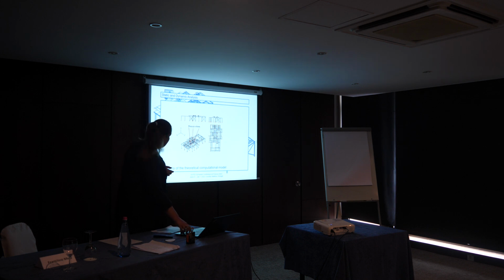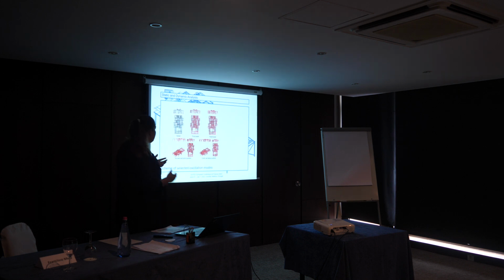So this is the first step. The second step was dynamic analysis. We introduced concentrated masses. I don't think that you can see them here. Concentrated masses in 3 directions. They simulate the masses of the robots.